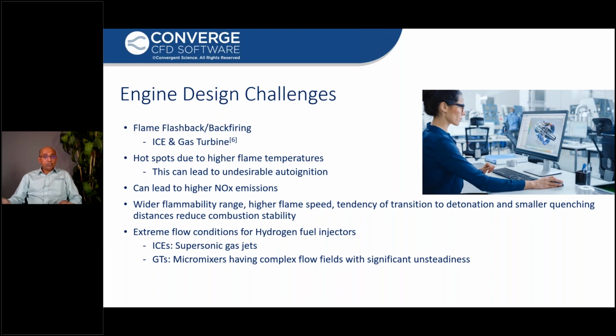There are some flow-related challenges also with using hydrogen as a fuel. Direct injection of hydrogen into ICEs typically results in high-speed jets that are supersonic. And micromixers in gas turbines can result in complex unsteady flow fields that need to be carefully assessed.